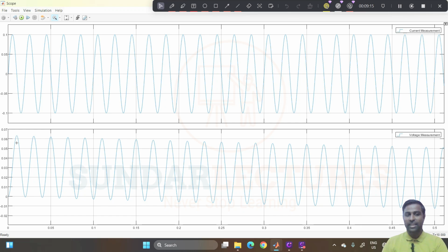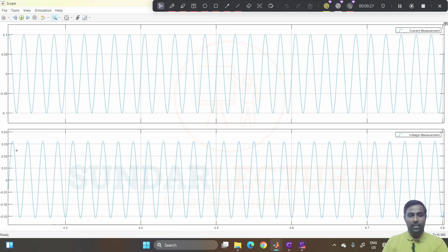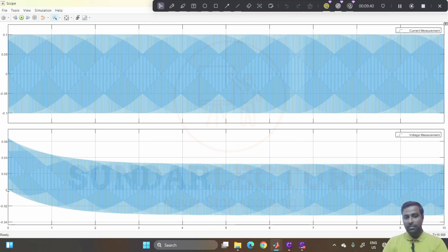But what will be the steady state voltage? You try to understand. You just click this and then you click this one. You will get a graph like this, and you select this particular thing. You see you are getting 0.03 volt as the steady state voltage. But you can easily see the transient period here. See, it is starting from 0 and it increases. Voltages are there across the capacitor, and then it is getting down to the steady state condition.